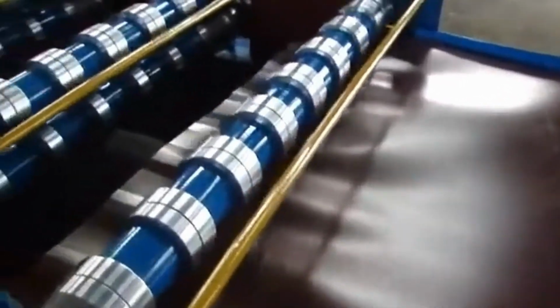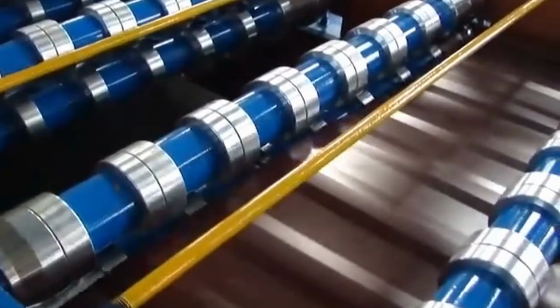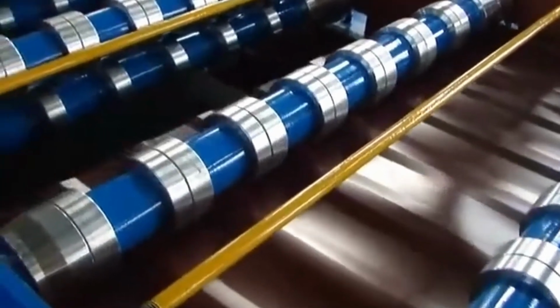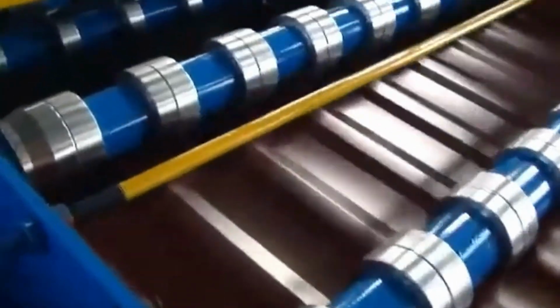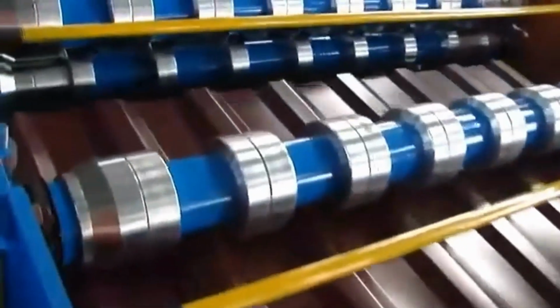And this is what you can mostly find on lines for the production of corrugated sheets with a low corrugation height. Its essence is that the metal strip entering the first stand of the rolling mill is subjected to simultaneous deformation along the entire width, and all the corrugations rise simultaneously. And from here follows one of the main disadvantages of this method. The metal has nowhere to be pulled to the center or to the neighboring corrugations.